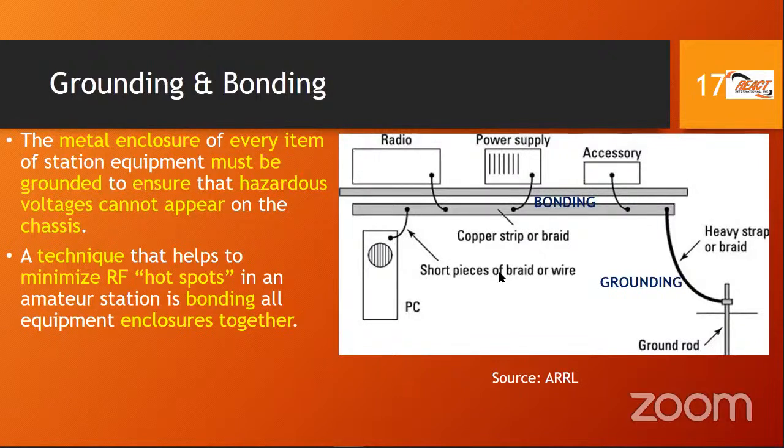All right, fair enough, you can say that. But really, we need to understand conceptually what bonding versus grounding is about. It's the same thing in a way, but let's define what they are about. They are closely related. First of all, every metal enclosure in your station, so this could be your radio or your transceiver, a power supply that may be connected, an antenna tuner, or an amplifier, first of all, all of the items must be grounded.